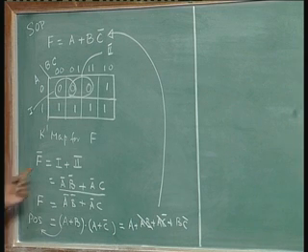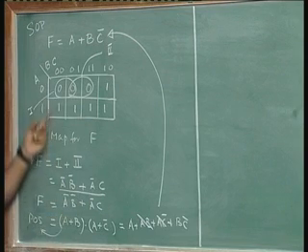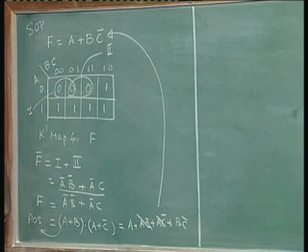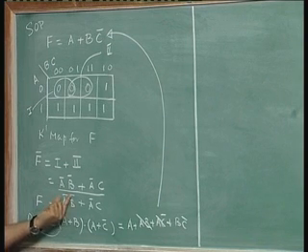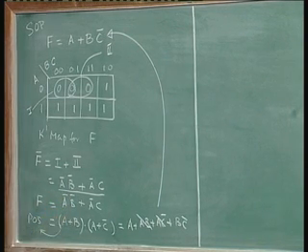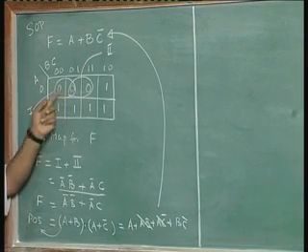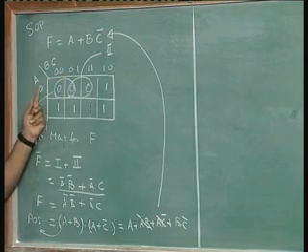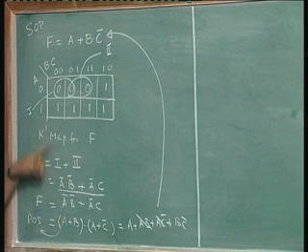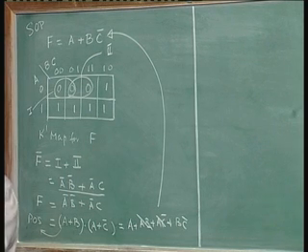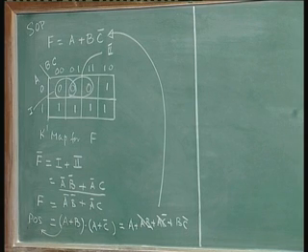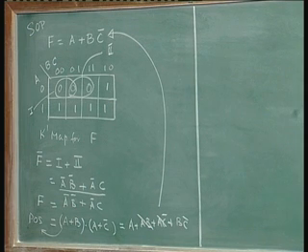But you can do one more thing, you can skip this by reading judiciously, because A or B corresponds to this, you will read it, because this I can do mentally, writing A bar and B bar and taking its complement, knocking off the bars here and putting an OR. All this can be done in my mind. I can see that whenever two zeros are together, this is A bar and this is B bar, I can write this as, instead of A bar I will use A, I will use an OR symbol, and B. That means I will read the map as if I would read a product term. I will read a sum term as I would read a product term, except that I will remember to complement each variable and remember to complement each operation. AND operation will be written as OR operation and variables will be written as their complement.